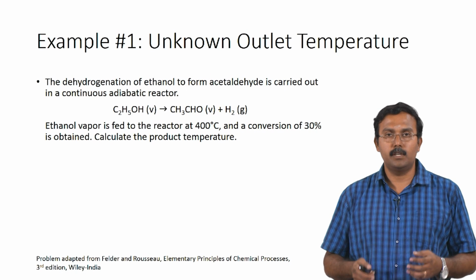What is important is that because we have a closed system, here we would also have to account for internal energy change in reaction instead of the heat of reaction directly. If you remember, we have already looked at the correlation between the internal energy of a reaction and the specific change in heat or the heat of reaction. Using that correlation, we will be able to calculate the internal energy of a reaction and perform the necessary calculations. Let us now start with the first problem.